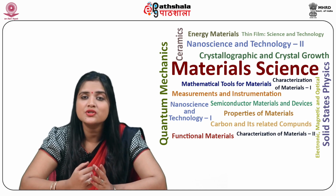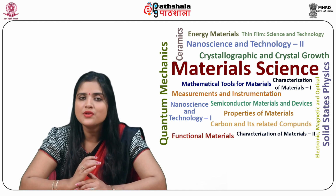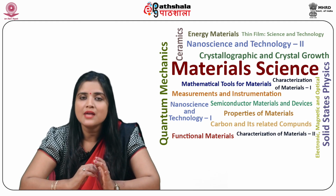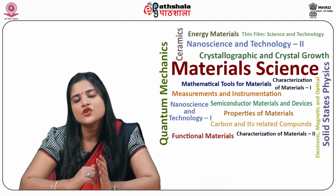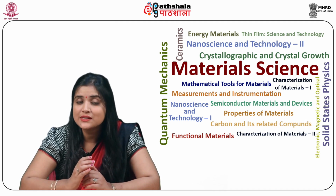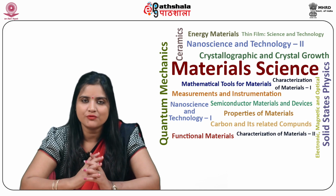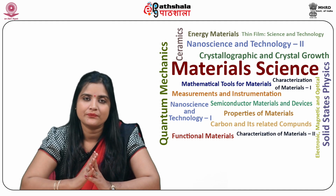We have already studied in the previous module Filters 1 that in a first order filter, the gain of the filter changes at a rate of 20 dB per decade, whereas in a second order filter, the gain changes at a rate of 40 decibel per decade. Thus, as the order of filter increases, the filter approaches its ideal behavior. That is, change in gain in the stop band of filter becomes more steep near the cutoff frequency.